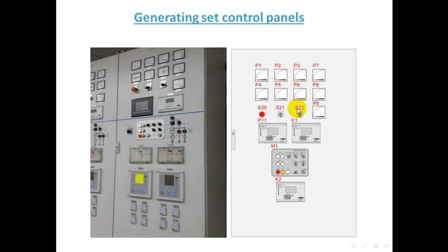S22 is the abbreviation for the engine or turbo speed measuring selector. Its function is to select the measurement of the speed of the engine or the turbocharger. If you want to look at the speed of the engine or the turbocharger in the generators through the control unit, you must press S22 to display it on the monitoring screen.